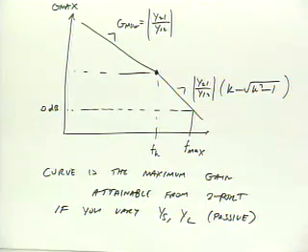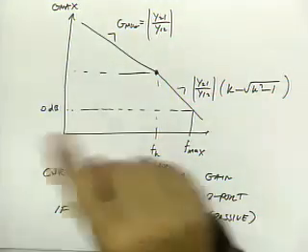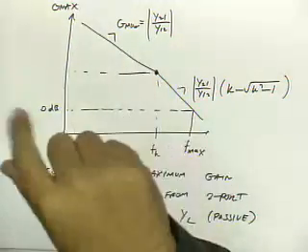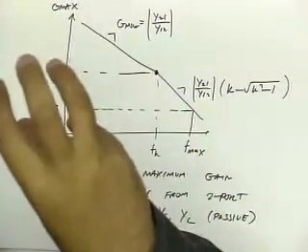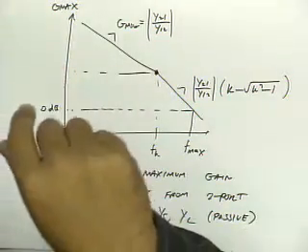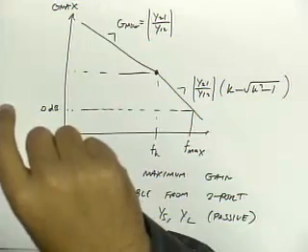Yes? At low frequency, the C mu should be an open circuit, right? Why is there a feedback? Good question. It's because there is a feedback path present, and there's lots of gain in the device. So I can pick a termination so that the loop gain of the device becomes bigger than 1, right?